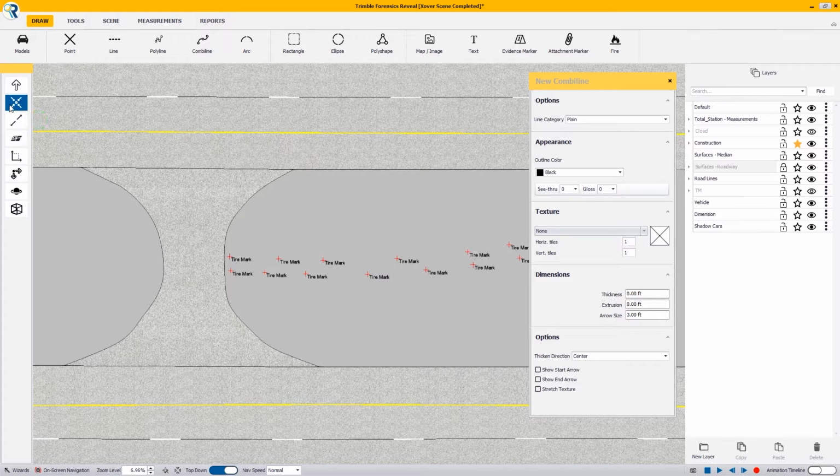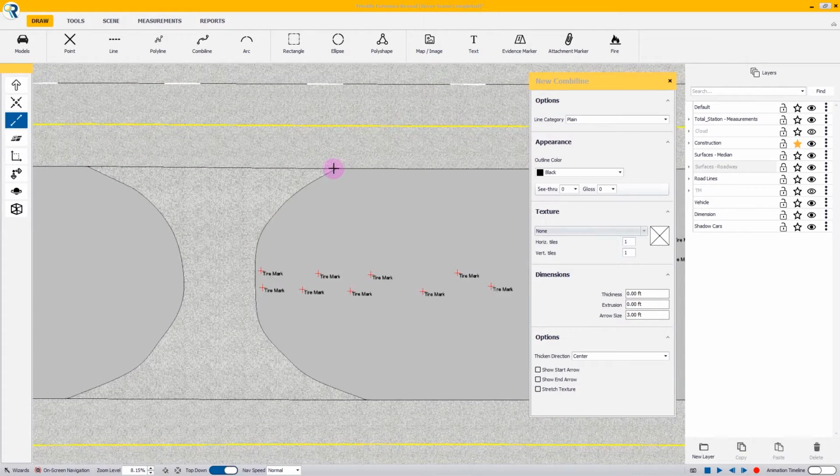And what I'm going to do here is a line snap. I'm just going to snap to our line here. And again, I'm staying away from my corner here. I don't want to get the corner. I want to stay off of it. So I'm going to click here.